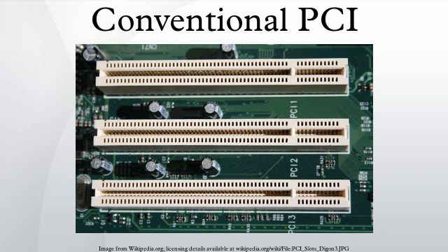Memory transactions between 64-bit devices may use all 64 bits to double the data transfer rate. Non-memory transactions may not use the 64-bit extension. During a 64-bit burst, addressing works just as in a 32-bit transfer, but the address is incremented twice per data phase.